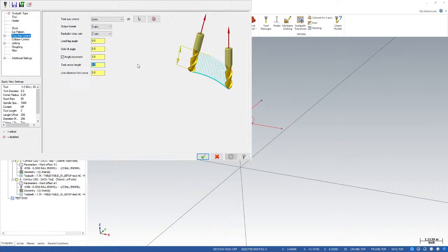Now, in some cases, we may need a higher precision for the rotary axis addresses, and due to rounding errors, we can actually change the length of this 3D vector. In the post there's mathematics to check the 3D length, and if it's not equal to a length of 1 unit, whether it's 1 millimeter or 1 inch, that vector gets scaled before the angle gets calculated.